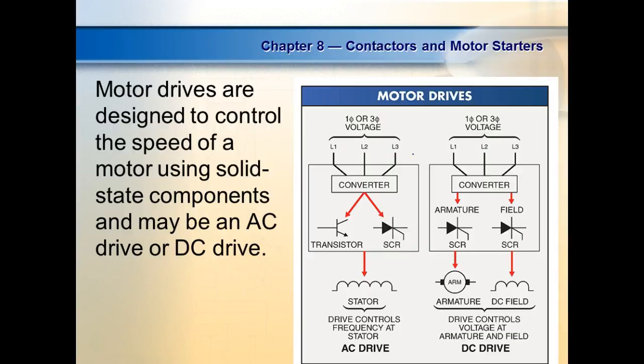A lot of times at U.S. Steel, the field was across the disconnect. It wasn't controlled by a relay. So they left the field voltage on it all the time. And they used to do that on purpose because the plant went down for a long time, and if they took the voltage off, the motor would get moisture inside and it would rust.